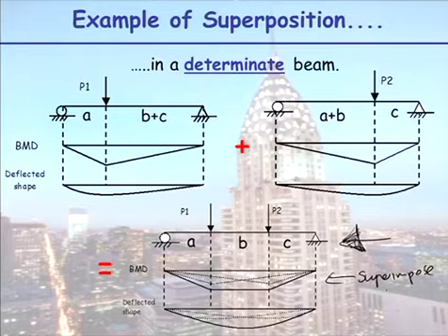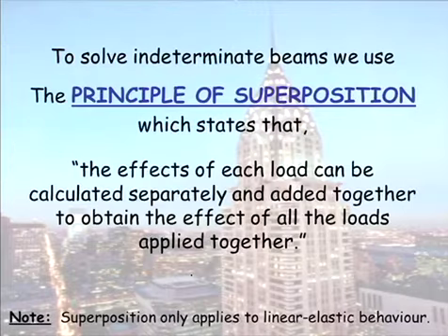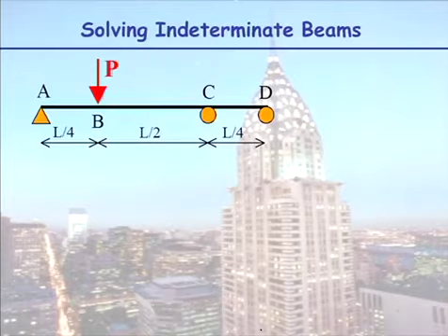And voila, you would have the correct bending moment diagram. So that is the principle of superposition. The thing to note with the principle of superposition, it only applies if things are linear elastic. Okay, moving on. So have a look at our beam here.